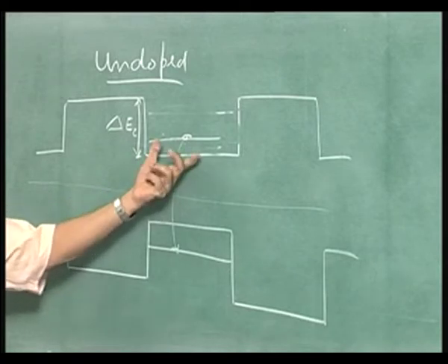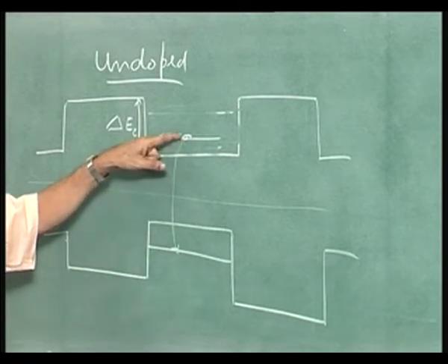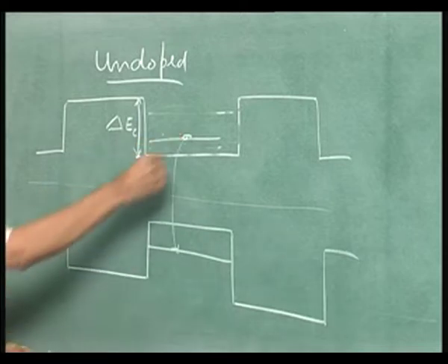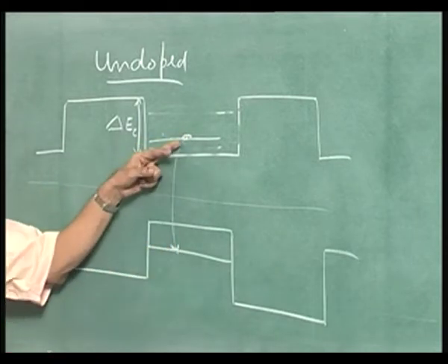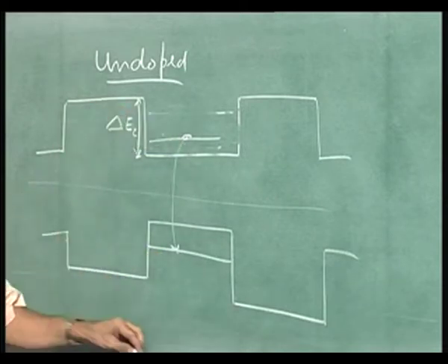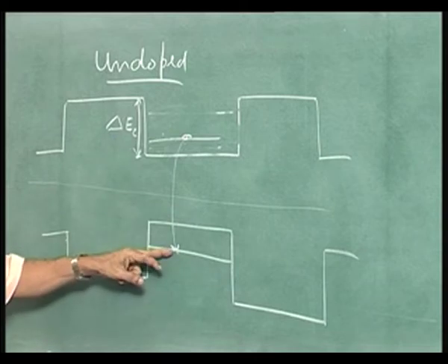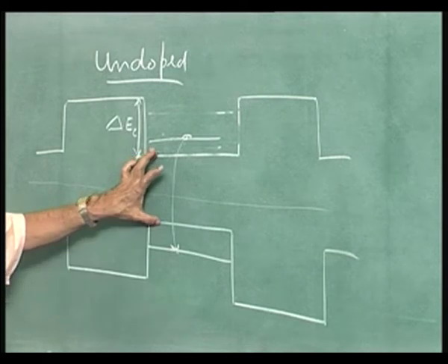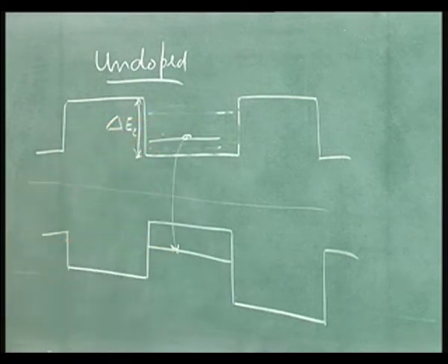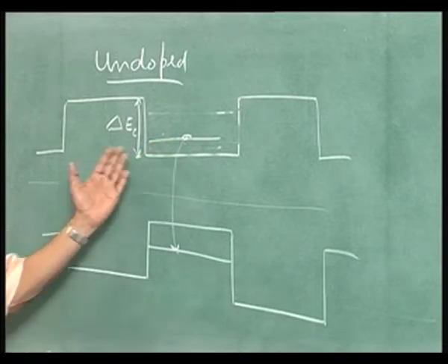When you confine them in a well like this, these electrons are above that band edge, that is the allowed level. Now, if you allow that to make a transition, that is when they recombine, they will get transferred from this level to that level, and the gap is more. So, if the gap is more, what have we achieved? The light emitted from here to here actually has a wavelength less than that corresponding to this wavelength, because energy is more, wavelength is smaller. That means you are pushing towards the visible range. So, you can get light of different wavelength by making combinations of these things.